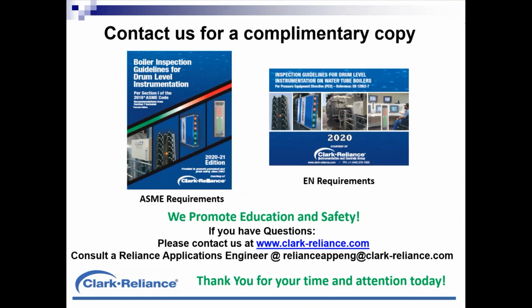Once again, if the operating level changes significantly lower than it was intended to operate at, the float will typically ride high, causing a false high indication relative to what's in the drum. Good question, though. Thank you.